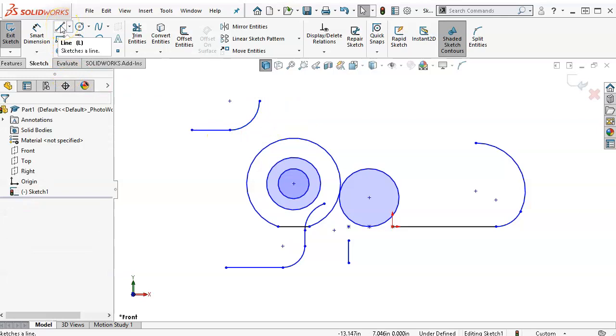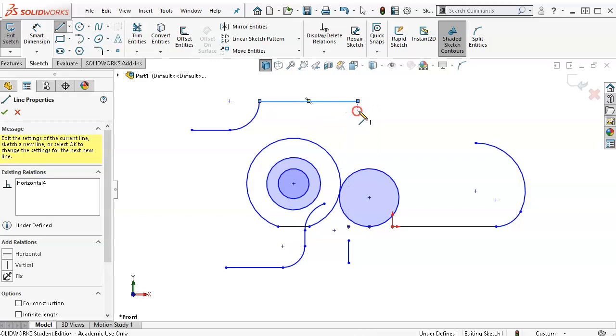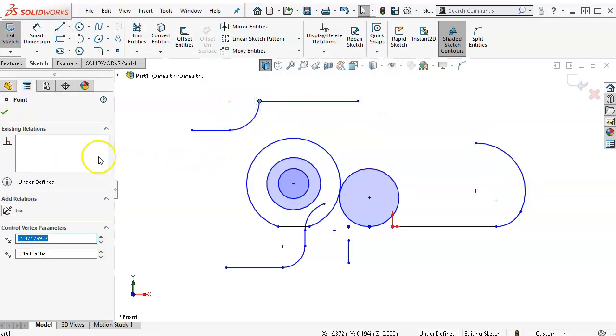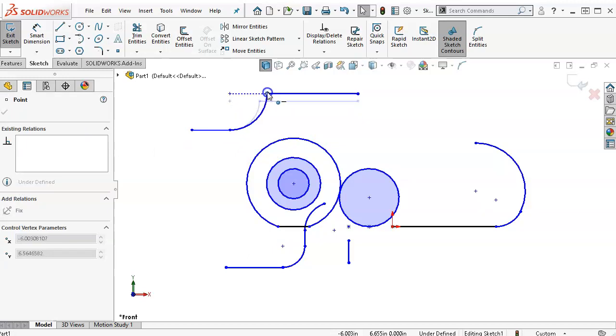So the other thing would be the inference lines. As I drag around, I'm going to pick up other pieces of geometry. So when I snap to, that's going to show concentric as a relation, but pretty much it's going to merge. I don't believe we end up with a coincident relation there. So that's a little bit confusing, that when we merge those points and it shows concentric, it's not really doing anything, and merges the one relation that does not produce anything in the list. There is no merge listed over here. They just connect, and they're sharing that point. They're merged.